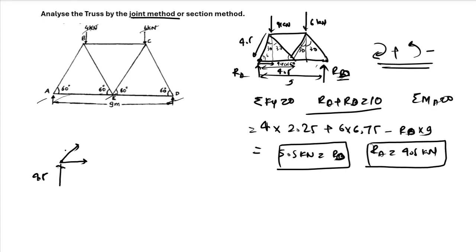As I was saying, the internal forces are, let us say, in this section AB. If you section this beam somewhere here, then the force inside the beam should be an internal force. Similarly, every member of this truss has an internal force, and the force which you see on the body is an external force. So we need to calculate the internal forces in the members. We will always take them as tensile forces. So this is one assumption we are making.